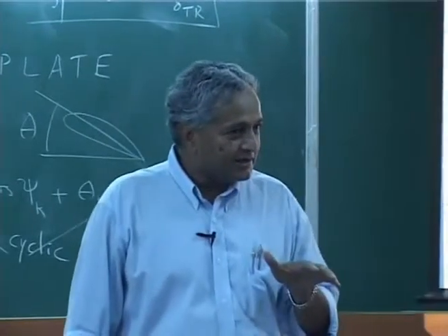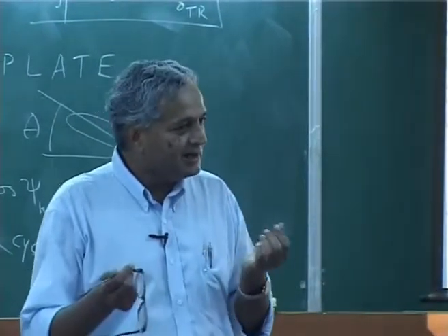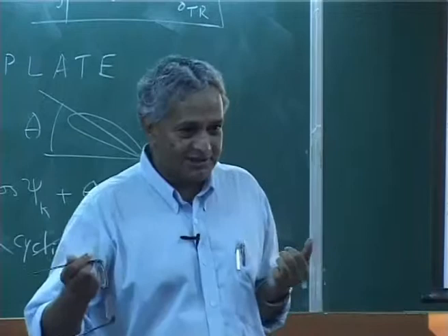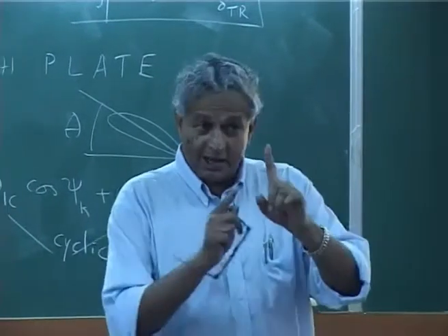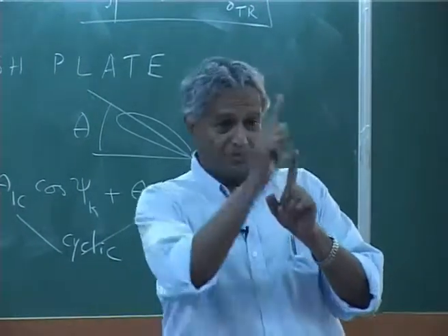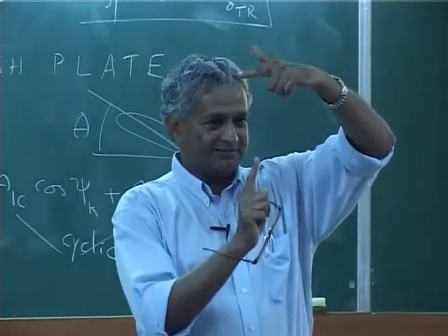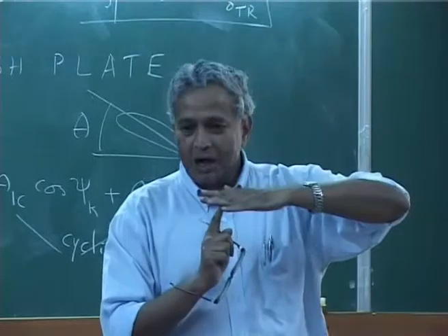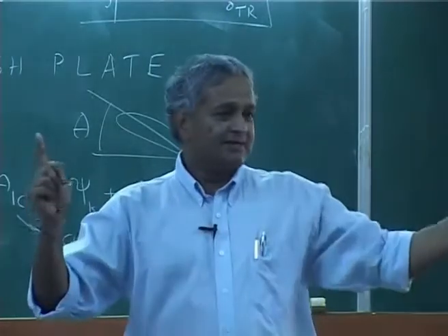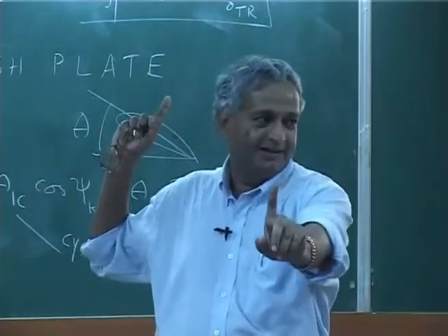Because if one rotor produces a little less torque than the other rotor, because they are contra rotating, please understand, both do not rotate in the same direction when you have two rotors, whether it is contra rotating one below the other, or side by side, or one behind the other.